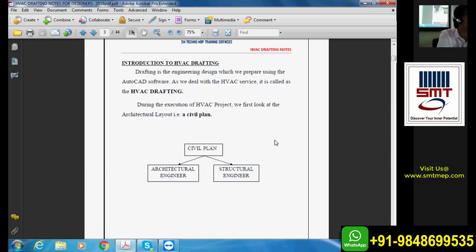All right, your pipe or your duct can come from there, or it can pass through the middle like this. You are the one who decides that. You have to check all the physical parameters like friction, velocity, and what else is there? You have roughness. All right, you have the CFM margin. All right, you have so many considerations to take place, how the airflow is moving, how the distribution is coming, if there is a lot of noise inside the circulation of the duct. All these parameters are going to help you make one particular duct.